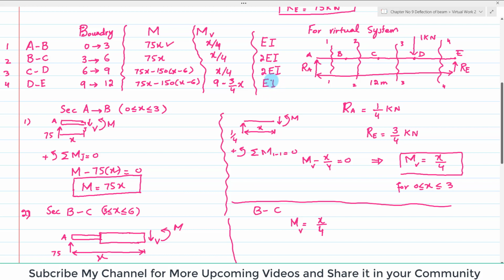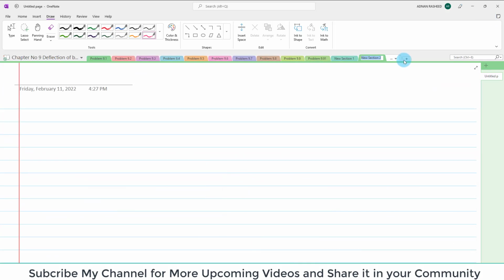Now you have completed this table, so we will move further in order to find the deflection, and we will use the same table below. Instead of going to another one, I will use this so that we can switch easily. As we know, deflection is equal to the integral between two limits of m into mv divided by EI into dx. This is the general formula between two points.